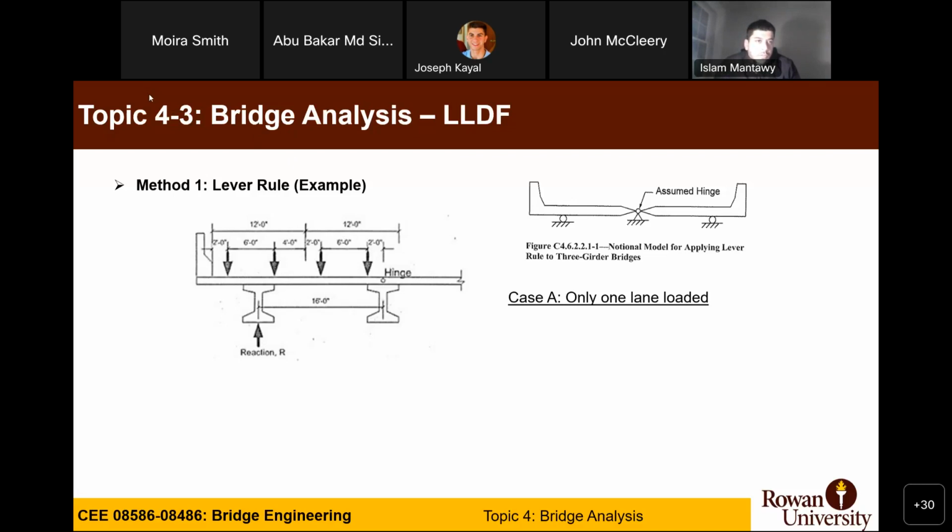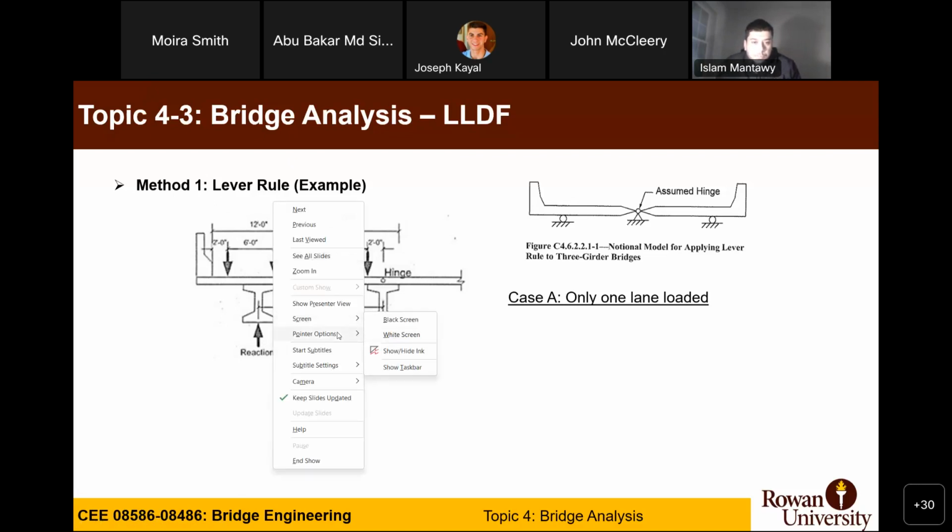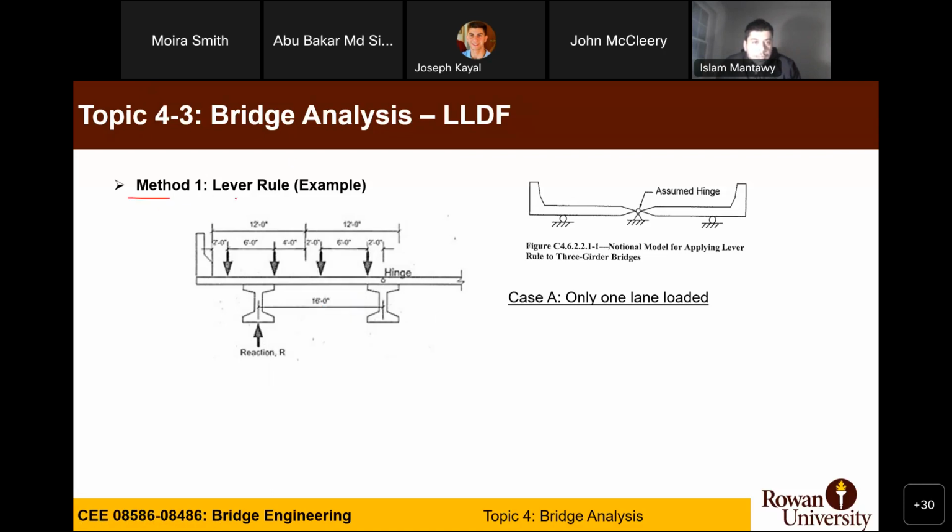Okay, let's resume now. I think it's 8:25 now. This is a level roof, similar to what we discussed last time. Let's have all of you start solving some problems with me. This is the case where you have a bridge. The spacing for this case was 16 feet, which is too high. I think it was from a very old example; I think they limited it now to 15. This is the exterior girder, and this is the interior girder. This is the location of your internal hinge.